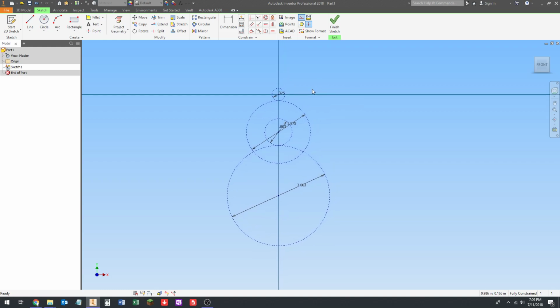Next, we need to know where the motor is going to be up here, so that we can make sure the aluminum plate that makes up the major structural component of the gearbox is big enough that the motor can bolt to it. So what we're going to do is draw another construction circle right here on this top circle, and we're going to make this the outside diameter of the motor, which is 1.756 inches. This is a 775 Pro motor. And I'm going to press the Enter key.